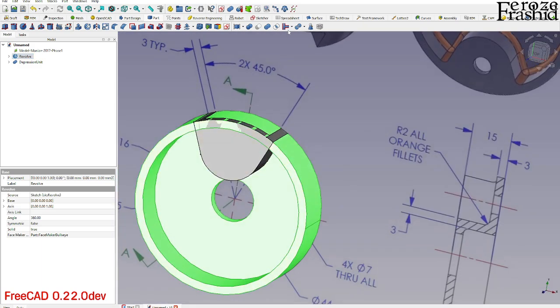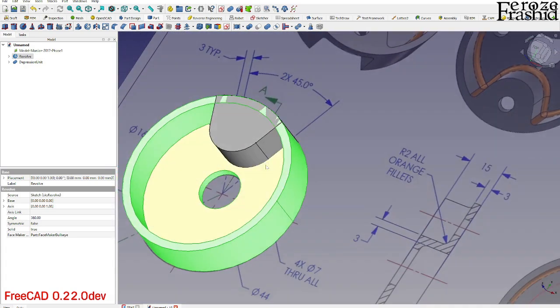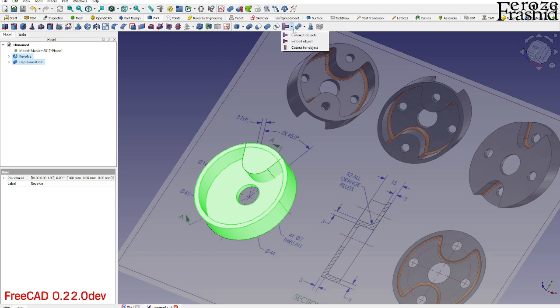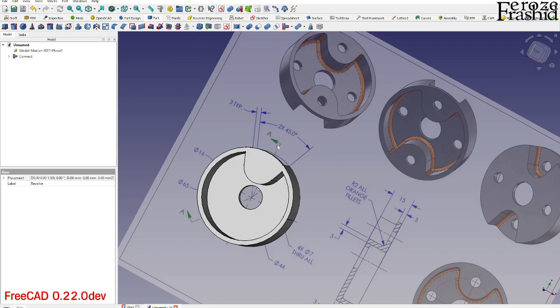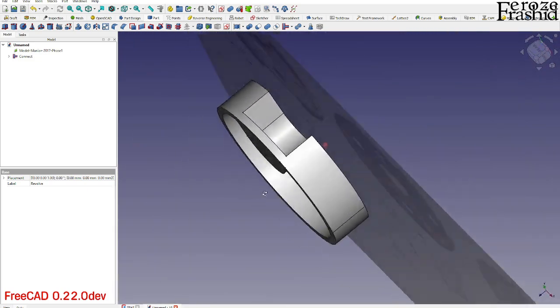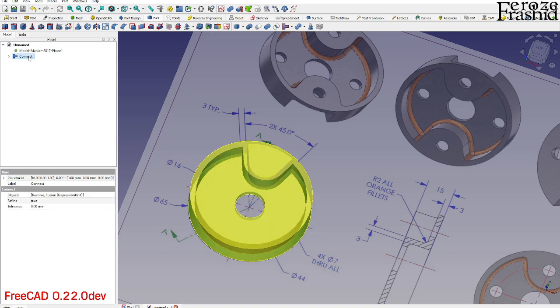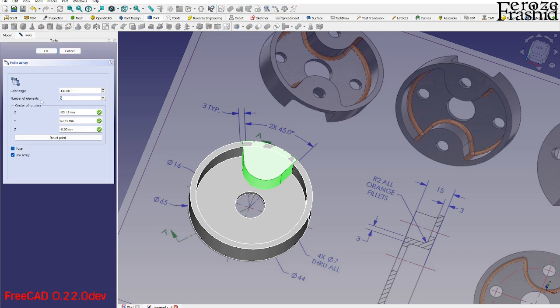Okay, and now bring the revolve back. Let's see if connect tool does its magic and make a good connection here. So take these 2 and come here and say connect object. Oh, it did. Pretty cool. That's all we wanted. We have this, right? But we don't want to do this right now. I want to do it after I array it 2 times.